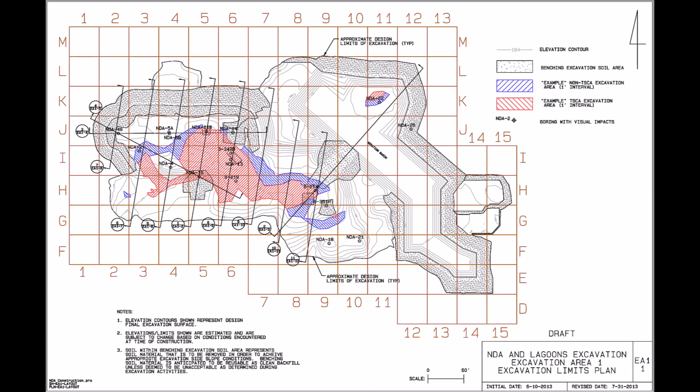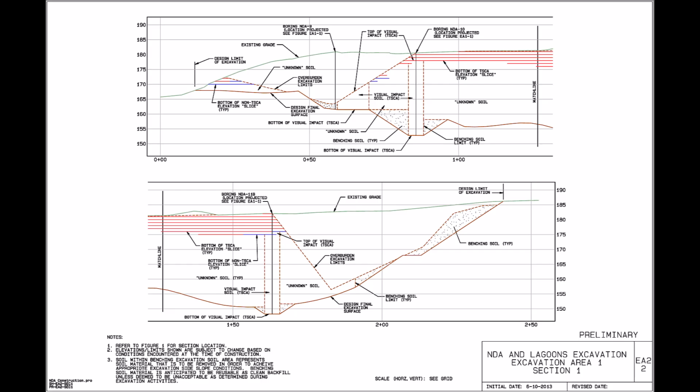Model outputs were exported to TerraModel earthwork design software for detailed excavation engineering. The resulting design surfaces define clean overburden, reusable benching soils, and PCB-impacted material as distinct stratigraphic zones across the full 50-foot excavation depth, broken into 1-foot slice intervals for contractor planning.